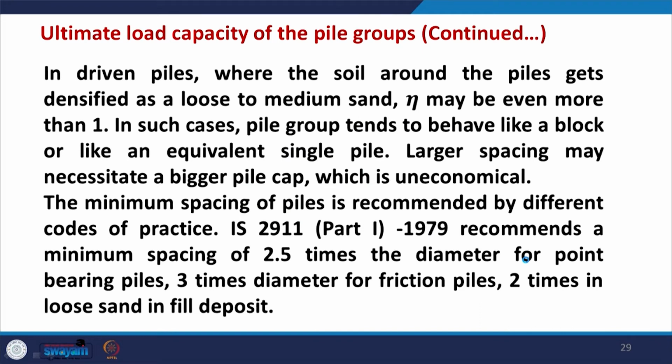Now, continue with the ultimate load capacity of pile groups. In driven piles, where the soil around the piles gets densified as in loose to medium sand, eta may even be more than 1. The reason is that when you use piles in a group, driving the piles densifies the soil, and once the soil is densified it may result in a value of eta more than 1.